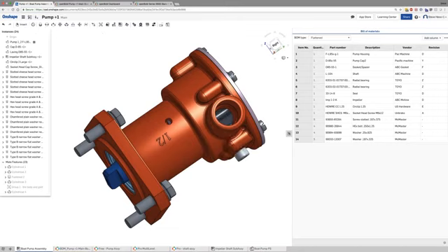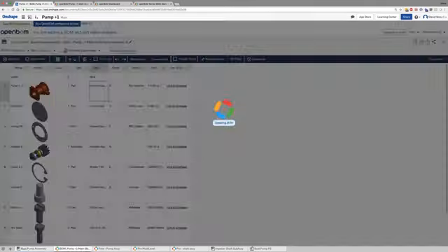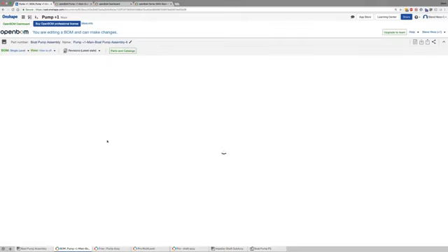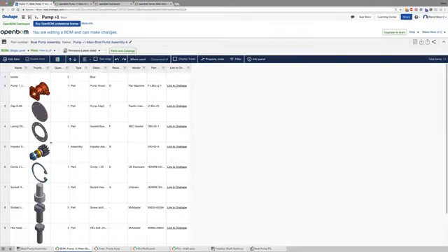And just to demonstrate the persistency, let's go back and update the part number for the shaft in our Onshape model. And what we will see is that the information for the shaft has changed, but the Loctite that we added has remained persistent. So that is a really nice feature.